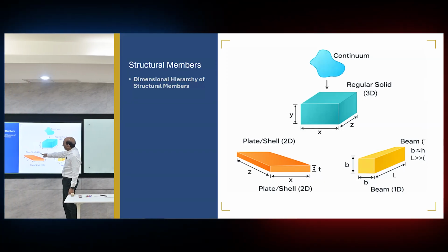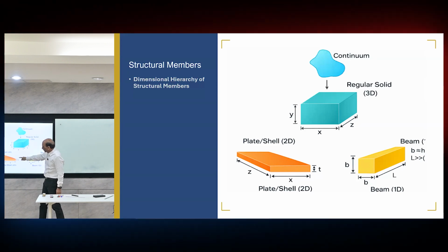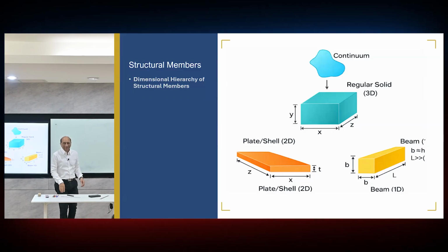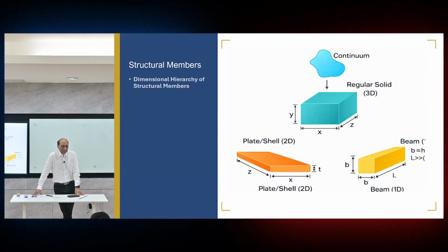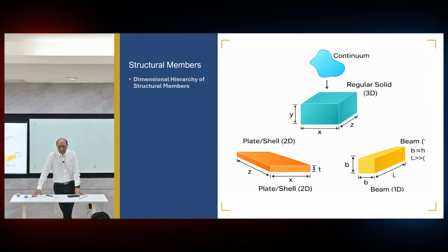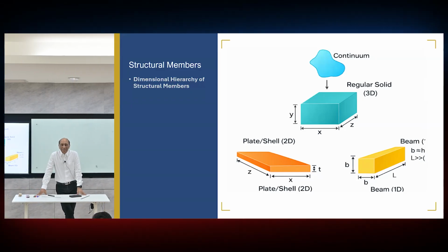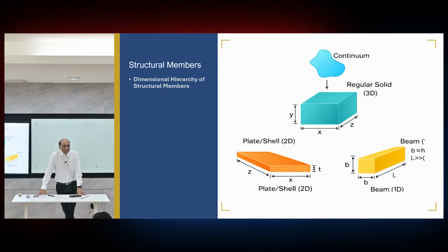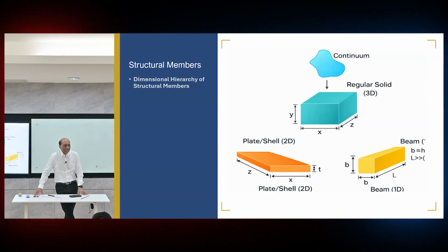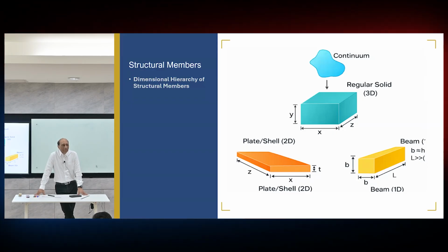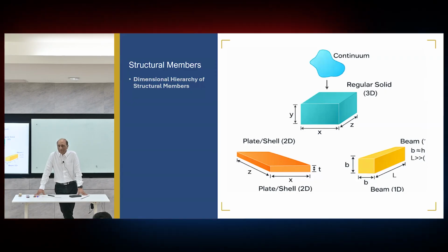And then we further say, okay, this is a plate and this is a beam. Because if you say this is a solid XYZ, but the thickness is too small compared to the other two dimensions, I will call it a slab. And then I will design and model it differently from if it was very thick. And where is that line drawn? Arbitrarily. And if the length of the thing is too long and the other two dimensions are small, I will call it a beam. Even though it is the same solid, just the dimensions are different. So we start calling them by different object types, and then everything from there changes. We start following different rules for the design of slabs or plates, different rules for the design of beams, and then different for trusses and struts and so on. Just because we look at their geometry and start making decisions.